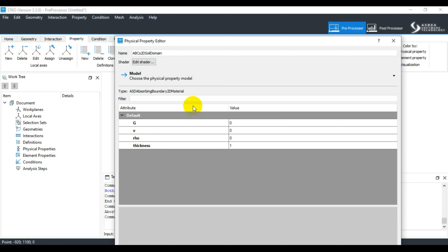So for shear modulus, if you have Poisson ratio and you have modulus of elasticity, then you can calculate this from engineering mechanics equations, and it's not difficult. It's just a simple equation that is G is equal to E divided by 2 into (1 plus nu).